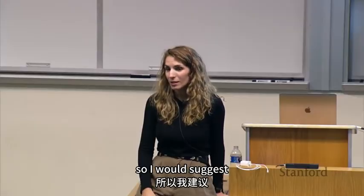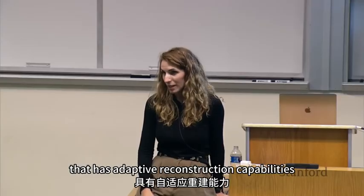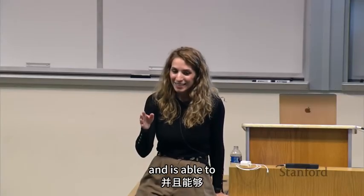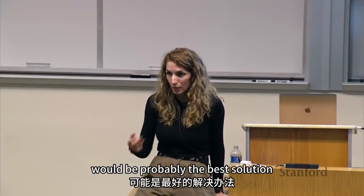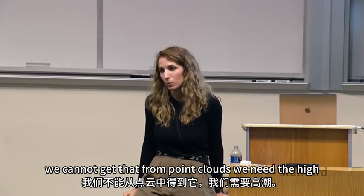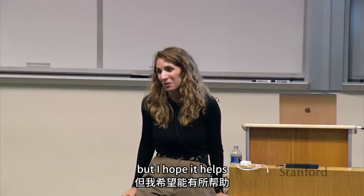So I would suggest, if you want the perfect data, a laser scanner that has adaptive reconstruction capabilities and is able to perform this in a fast iterative manner would be probably the best solution, and getting images as well, because we need images to understand materials. We cannot get that from point clouds. We need the high frequency information from the images. I know I'm not answering exactly your question, but I hope it helps.